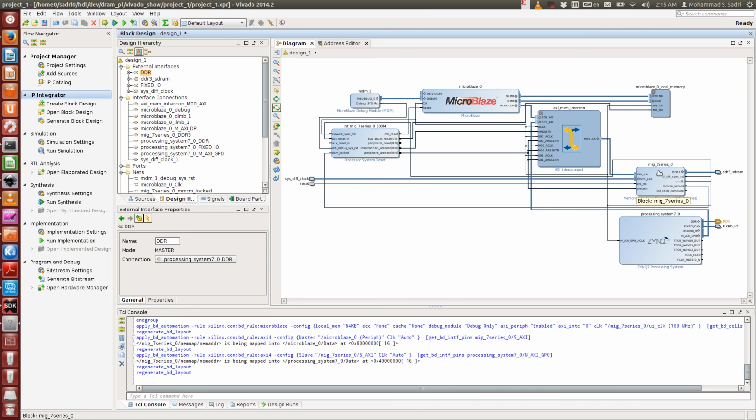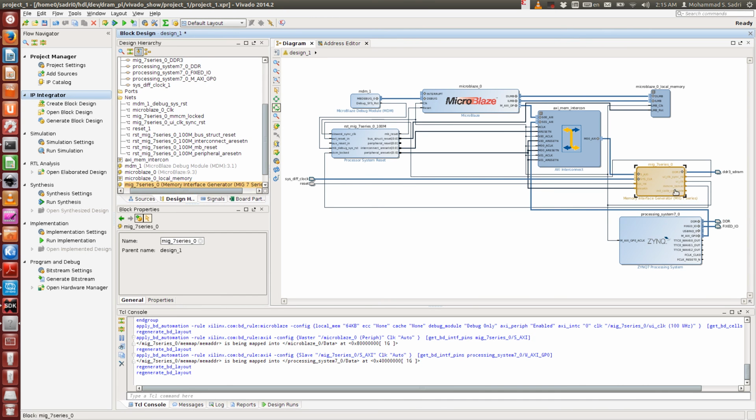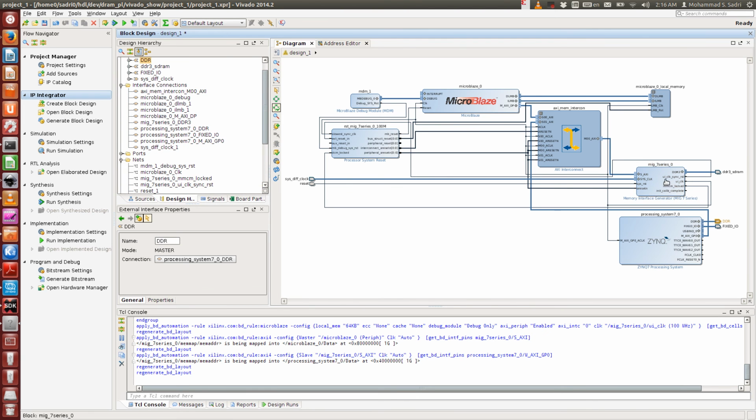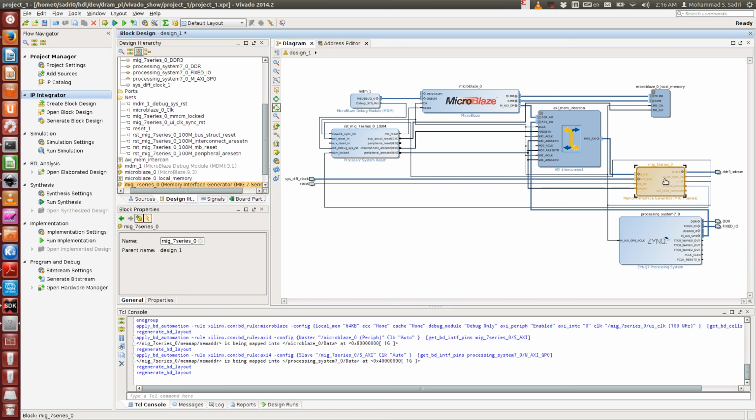What we are doing in this video is different, because we are using the DRAM memory on the PL of the ZYNQ device, instead of the DRAM memory on the PS, to share the data between the accelerator and the ZYNQ device.